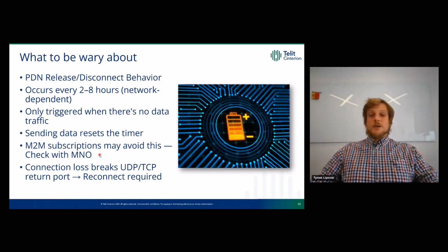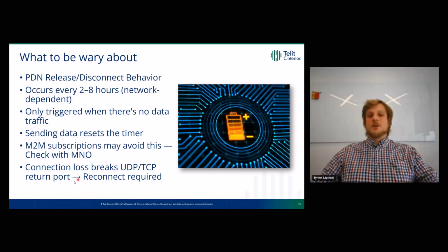What happens when the network releases or disconnects the PDN? Well, the connection loss will break our UDP or TCP return path. So we need to do a reconnect, because essentially we have lost the pipe between the modem and our server in the mobile network operator infrastructure.